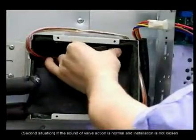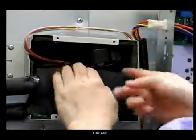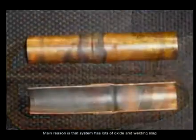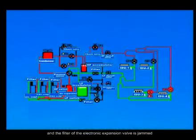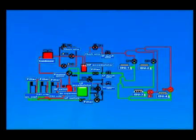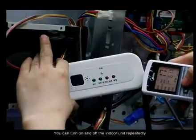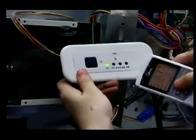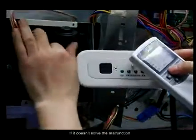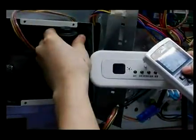Second situation: the sound of valve action is normal and the installation is not loose. Causes: the main reason is that the system has lots of oxide and welding slag, and the filter of the electronic expansion valve is jammed. You can turn the indoor unit on and off repeatedly and feel the action of the throttle part and refrigerant flow by hand. If it doesn't solve the malfunction, you need to replace the valve and clean the system.